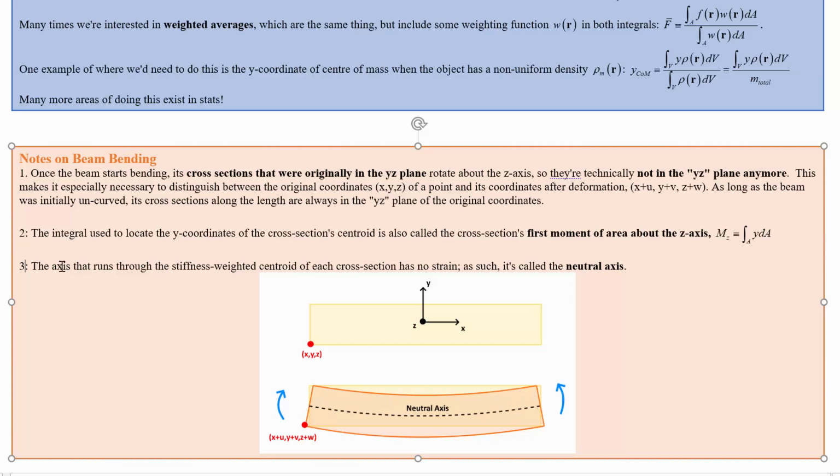All right, next, when we're bending like this, there's an axis somewhere in the middle that doesn't change length. To do this bending, you notice the top line has gotten shorter, and the bottom line has gotten a little bit longer than it was originally. So somewhere in between, there's a line that stays exactly the same length. It has no strain, and in fact no stress because of that. That's called the neutral axis. In 3 dimensions, it's the neutral surface or neutral plane through this material.